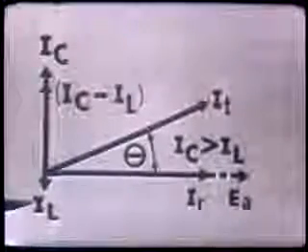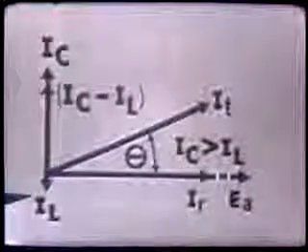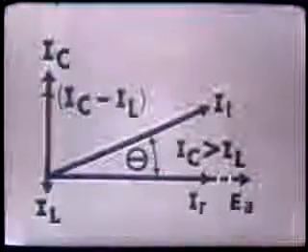And what circuit change could we make for this to occur? Well, to illustrate this point, I have a little demonstration set up. I have a parallel AC network similar to the one we have been using here in this lesson. Only I have each current in each branch metered. That is, our capacitive current, IC, our resistor current, IR, and our inductor current, IL. Now I have the circuit, as I said, connected to a variable frequency source where I can vary the frequency applied to this network.